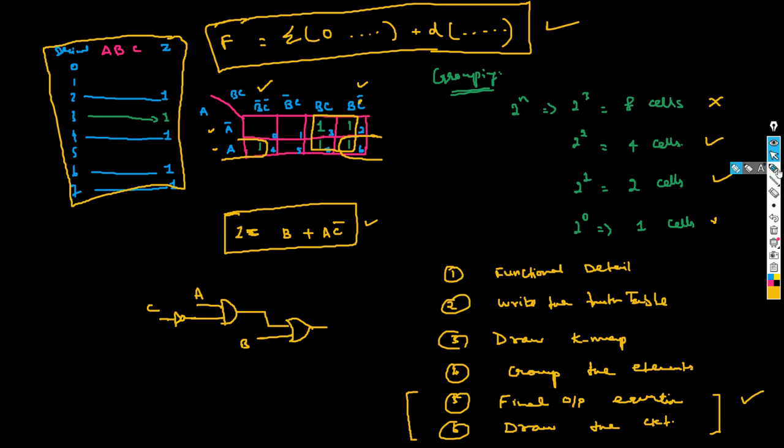You may have a sensor data connected to A, another sensor data connected to B, and another sensor connected to C. Based on these three sensor data, your system is expected to generate the output. You may not have control on the inputs, but when you optimize your circuit, you follow the schema and that helps you come up with the best possible circuit, which would take less area, or give better cell types, etc.